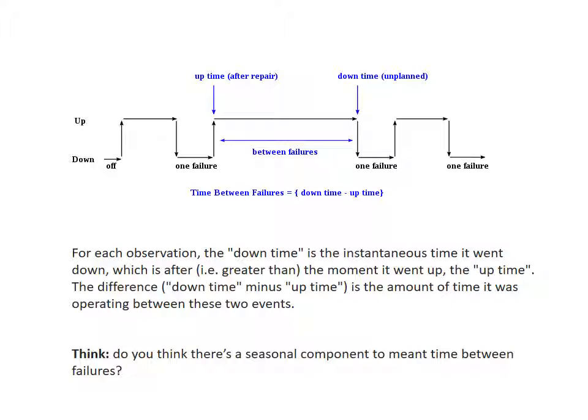And so this gives you a sort of binary signal, an up or down signal, and you can calculate the number of periods in between an up or a down, right? So assuming that you're able to tease out whether a power plant is shutting off because it's being forced offline or because it's just responding to some change in demand or market price or something else like that, you can empirically pull out the mean time between failures for different power plants, and that's one way of modeling power plant failures.